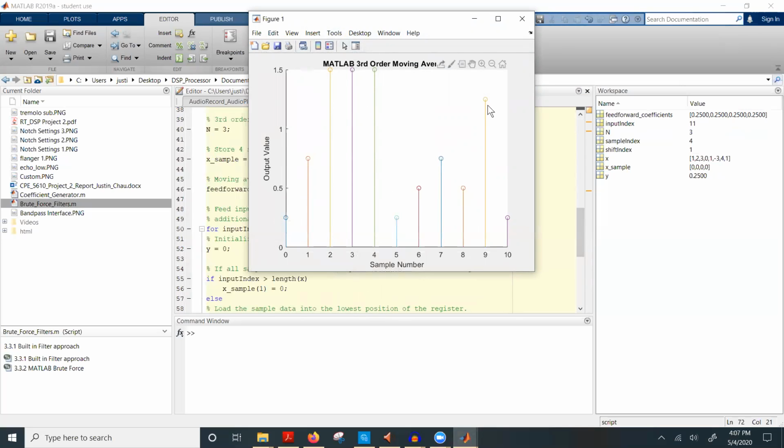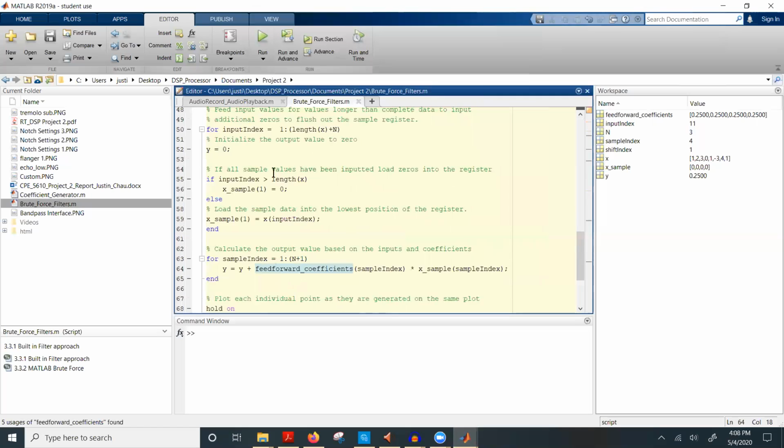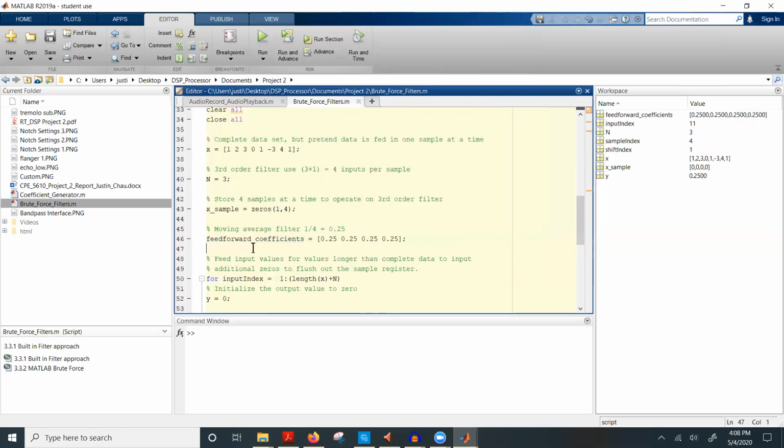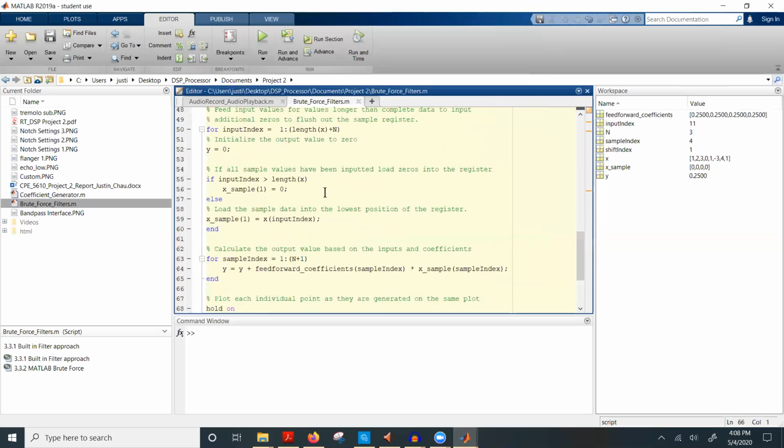as when we did the original MATLAB process, but that one can only be done offline in post because that one required all the data points at once. But this simulation doesn't require the data points all at once, and you can feed them in. So this will be a closer representation of real-time processing. And this is the approach that will generally be taken when programming in C. We will be looking at values in real time and storing them in buffers, and then performing the outputs, and then storing and shifting them in shift buffers.